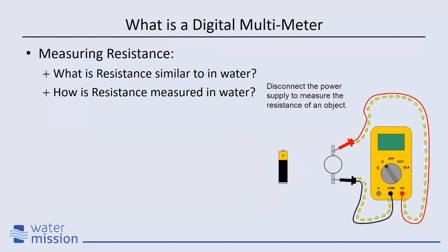Well, electricity is similar to that as well. If you want to measure the resistance of an item, you have to electrically de-energize it and isolate it from the system.